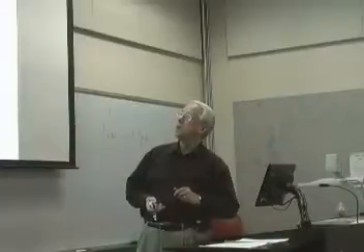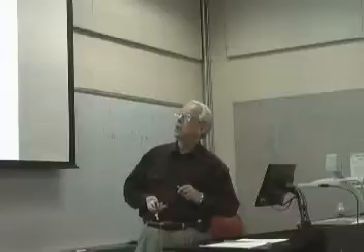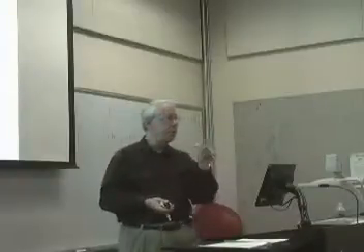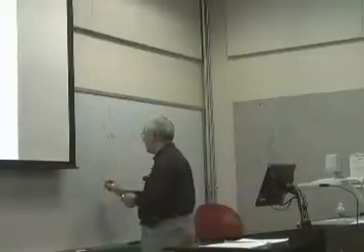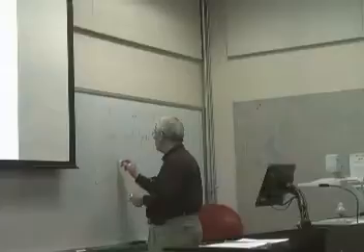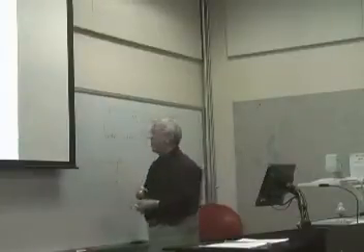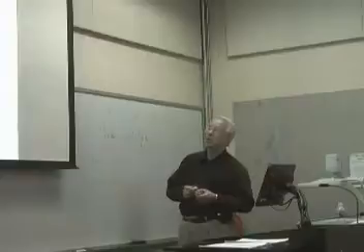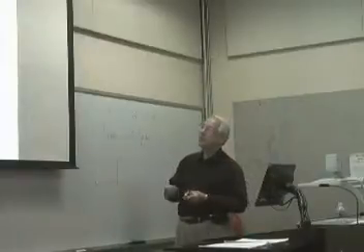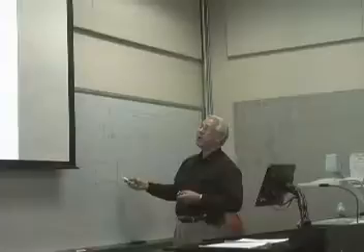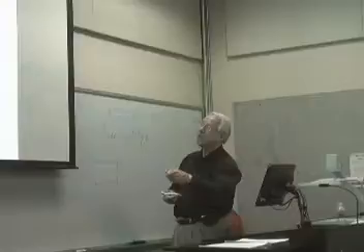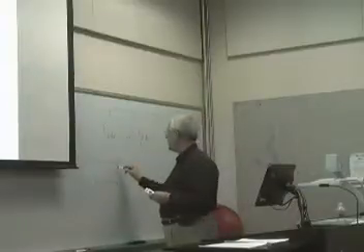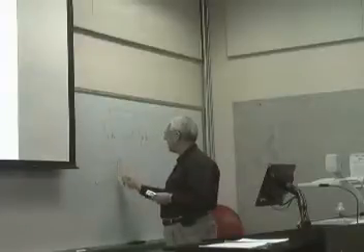This is what it looks like if you were the computer setting up a flux boundary condition on nodes 2 and 3. So if I had an element that looked like this, I would have node 1, node 2, node 3, and node 4. So I would have a convective boundary condition that would be setting between nodes 2 and 3. How do I know that? Because 1, 2, 3, and 4. So that means that that condition would be setting over here on this boundary.